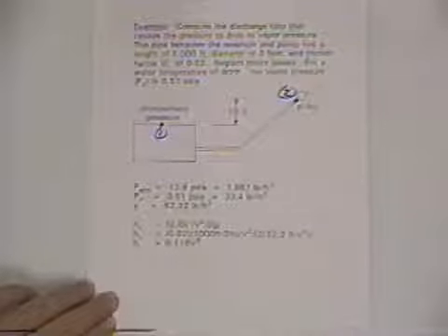As a matter of fact, if we jump back just a second here, in the Darcy-Weisbach equation, we plugged in the numbers, the given friction factor, the length of the pipe, the diameter of the pipe, the velocity squared over 2 times the acceleration of gravity, and we were able to convert all of these terms to a number. So the head loss is just a number times velocity squared according to the Darcy-Weisbach equation with a given friction factor. And so that's going to allow us to simply plug in an expression as a function of velocity for the head loss.